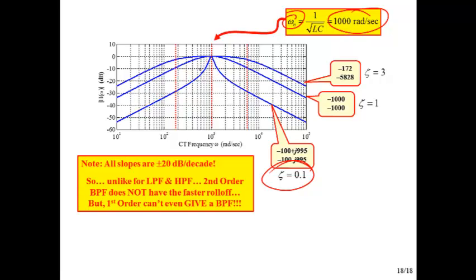So if I only want a very narrow band to pass, that would be the kind of filter that I would want to design. Notice here, though, if I want to pass a broad range, like maybe have this be some sort of audio range, 20 hertz up to 20 kilohertz, and stop very low frequencies and very high frequencies, then I would want the case where I have distinct roots, because it comes up, then it goes flat for a while, and then it goes back down.